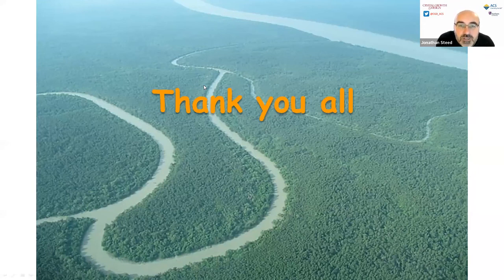Okay, great. And I think Pancho's got a follow-up. He says, according to your explanation, elastic crystals have isotropic interactions, interlocked, while plastic have anisotropic interactions, slip planes, based on theoretical results without experimental results of bent section. However, there are only two examples in the literature where bent parts of the crystals were analyzed using microfocused X-rays, and he gives the citations. Based on their experimental data, elastic crystals have anisotropic interactions instead of isotropic, and plastic crystal doesn't have any slip planes. Can you comment on this?